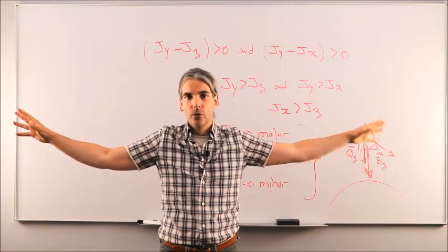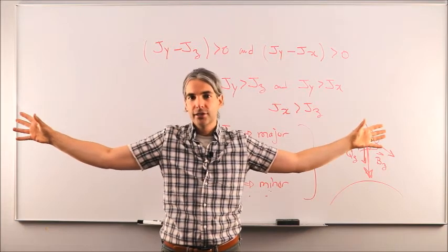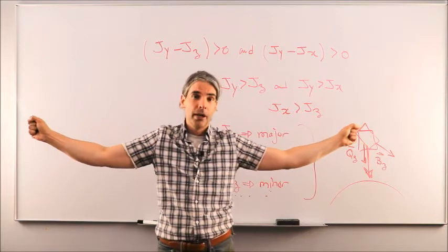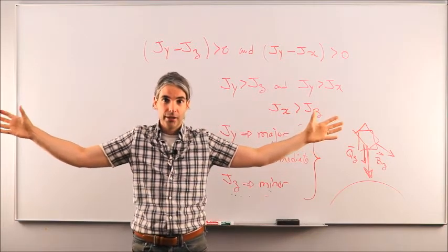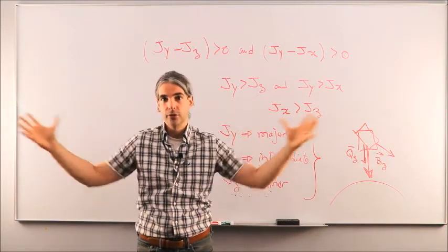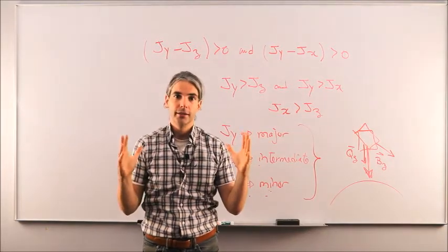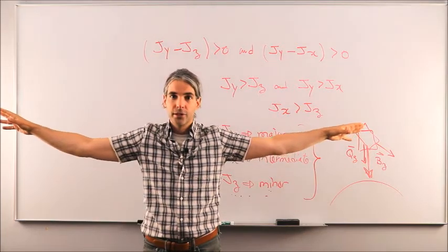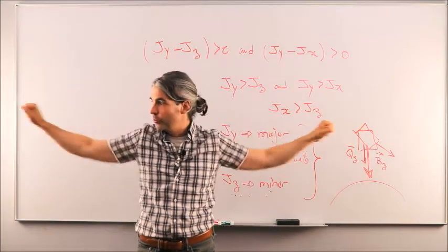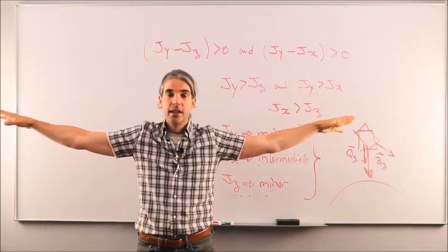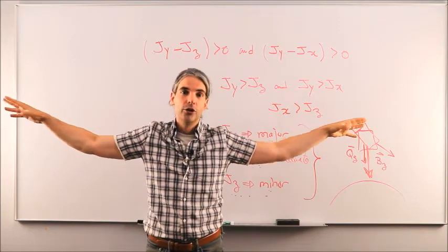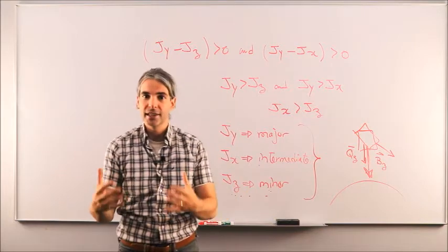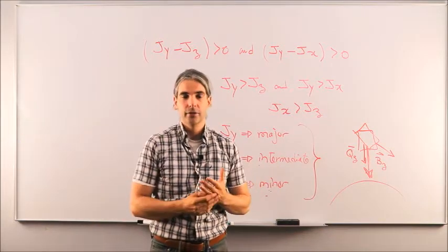At the end of both are big masses, such that all of a sudden the inertia matrix of the spacecraft is greatly changed compared to the case where those two booms were stowed inside the spacecraft. So you are maximizing the difference in principal moments of inertia by deploying two booms along a single axis, and thereby you maximize the gravity gradient capability to passively stabilize the spacecraft, okay?